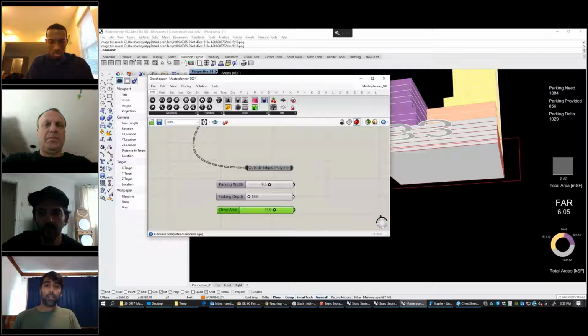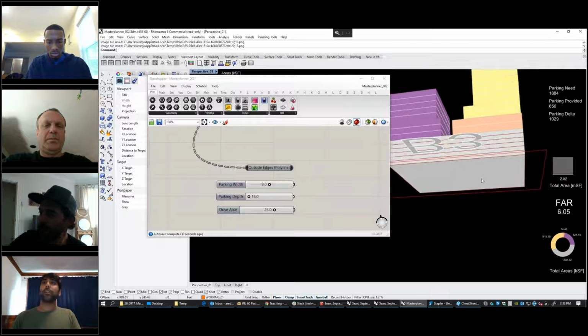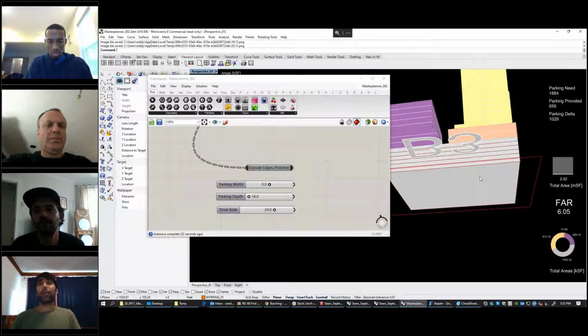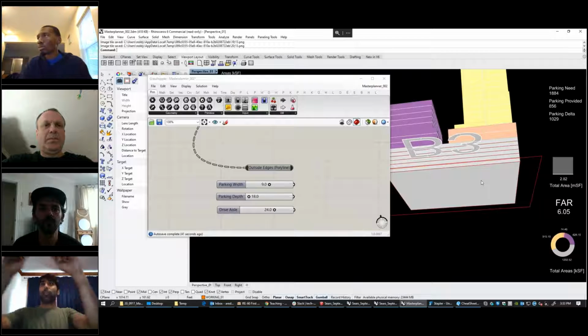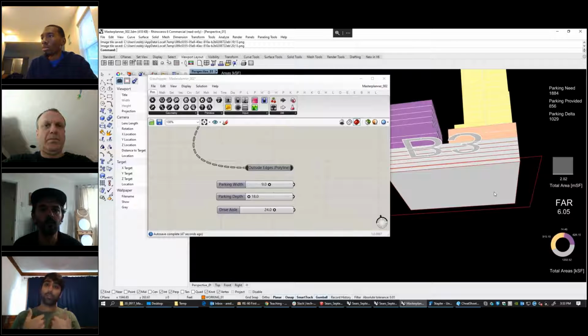And so basically I want to find a parking layout. It's pretty simple. The reason I did this is because even when you draw it with CAD or you draw it by hand, it's always the same process. It's the same sketch type process, at least for me: I'm gonna take the outside perimeter, line it with parking, find the inside, and then find an inside core that works for rows and rows and rows of parking, and what was the most efficient way to do it. And then you start putting your vertical penetration on top of that.